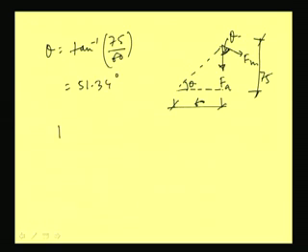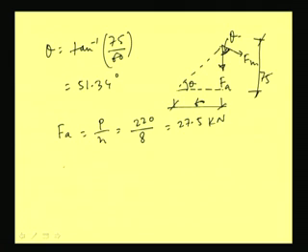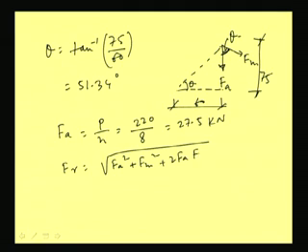Now, axial force we have to find out, Fa is nothing but P by N. So, P is 220 kilonewton by N, the total number of rivets, which is given as 8. So, this is coming 27.5 kilonewton. So, now we can find out Fr, which is nothing but root of Fa square plus Fm square plus 2 Fa Fm cos theta.